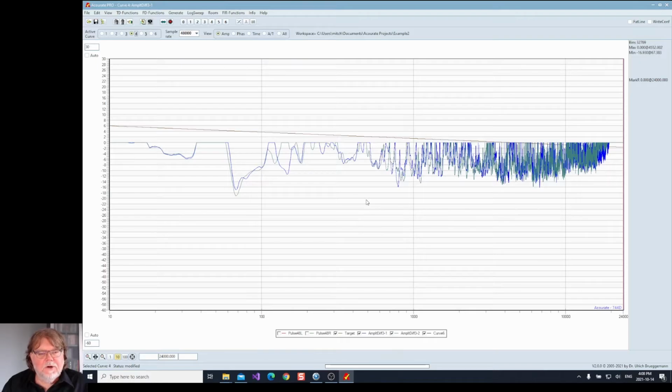Now, if we're wanting to apply a pre-filter, typically we only want to apply it at low frequencies. So how do we get rid of everything beyond a certain frequency? I've put a right marker around 200 hertz, and the idea is that we just want the left-hand portion from 200 hertz and below, not the right-hand portion.